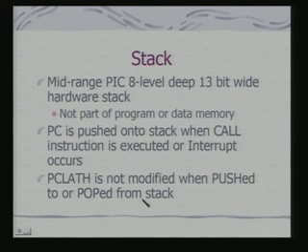The stack is 8 levels deep; typically mid-range PIC has an 8-level deep stack. That means what? It can store 8 values, 8 13-bit values. And obviously, the PC is pushed onto the stack when there is a call or whenever an interrupt occurs. Typically, the PC latch high register is not modified when pushed to or popped from the stack. What does that mean? That means effectively you are confined to the pages into which the memory is organized. So, this gives you certain restrictions in moving around the value of PC.